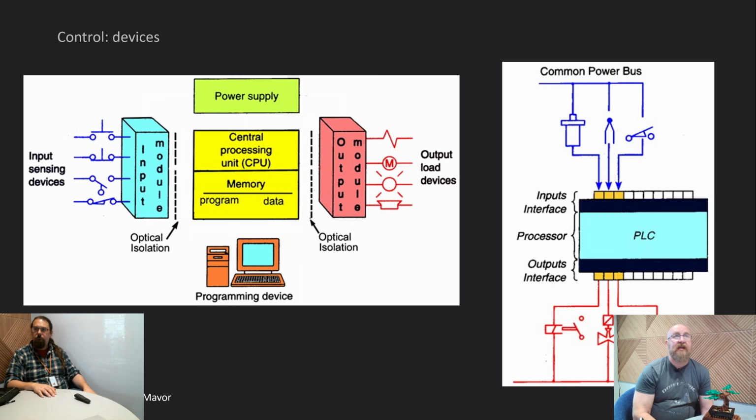With one PLC, you are likely going to want to control multiple different voltages. You don't want your current to be driven by the PLC itself. You want to be able to expand the amount of current your system is using as you add different devices. By making the power supply external to the PLC, it becomes much more useful for a broad array of applications.